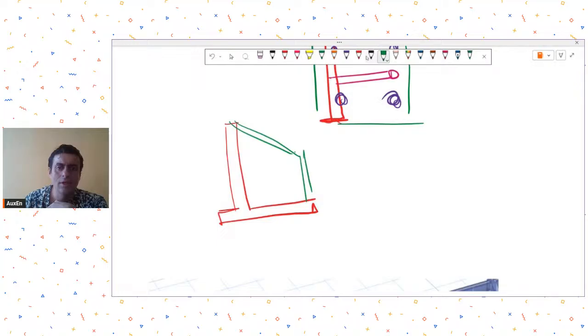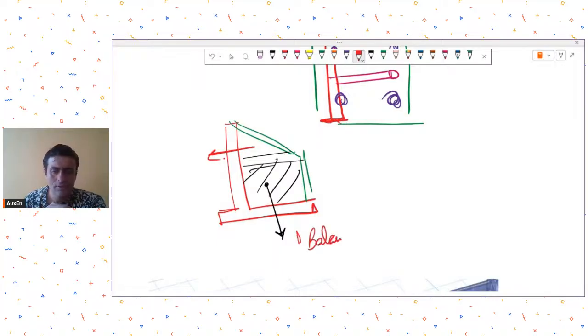Now if I provide the toe and heel slab, obviously there will be soil fill over here, which will add to the counterbalancing moment to the overturning moment due to lateral earth pressure. So because of that heel and toe, you will get the balancing or resisting moment. Balancing moment. You will be able to get it from there.